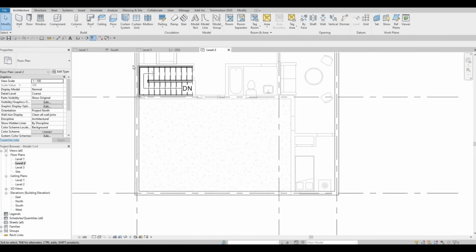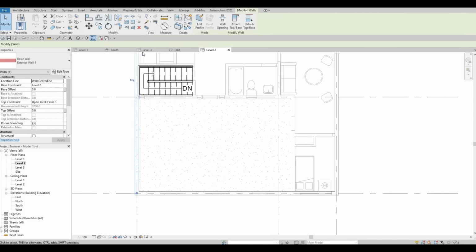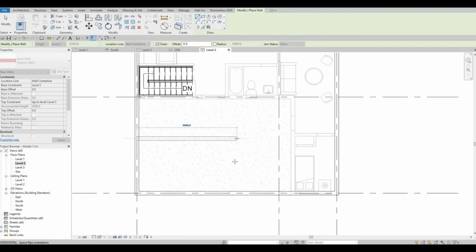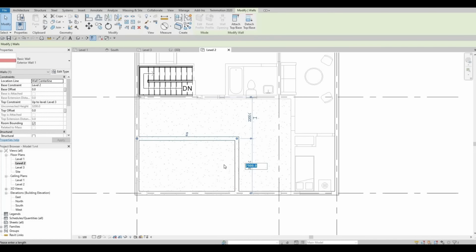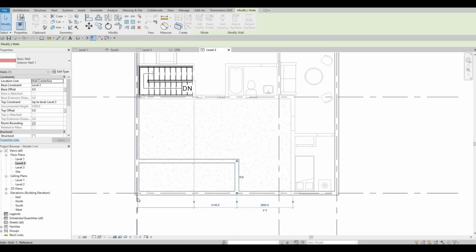And then let's use exterior wall number 1 again. So click this one and then CS. We're just gonna put it for now here and like that. After that, press escape, and this one should be around 1700. And then click this wall. This one, let's move it all the way to this grid line and around 4100.